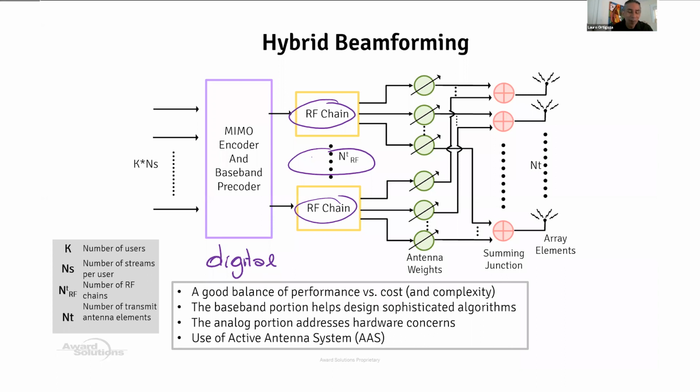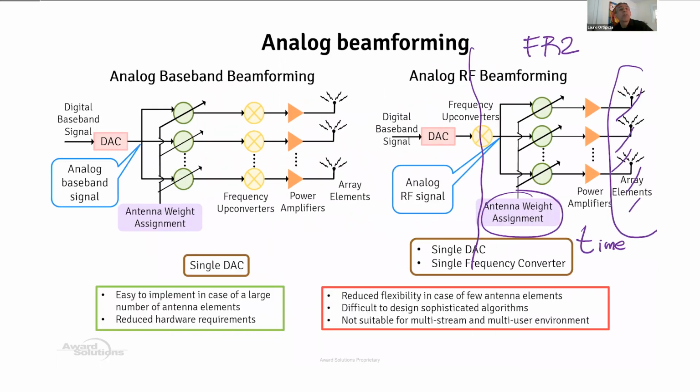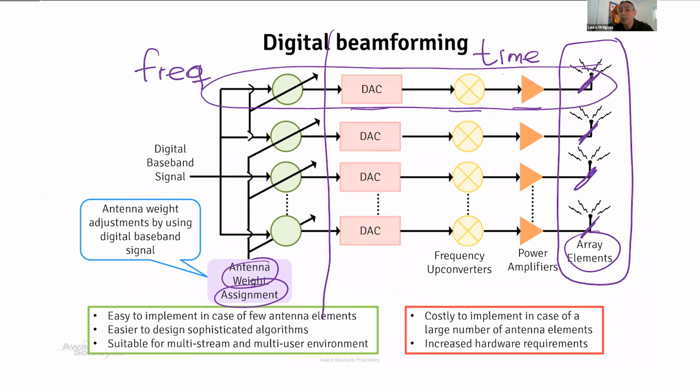Now, think about this, Manish. If I have 100 subarrays, ideally, I could produce 100 layers, yeah? 100 subarrays, 100 layers. However, currently, your vendors can only support sending 8 layers and the UE receiving 8 layers in frequency range 1. I haven't seen that, right? They only use 4 by 4. But ideally, if you could send 100 layers and if you have 100 subarrays, go ahead and do it, man.